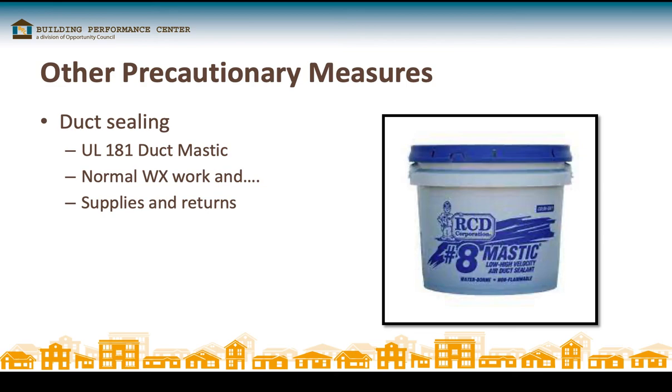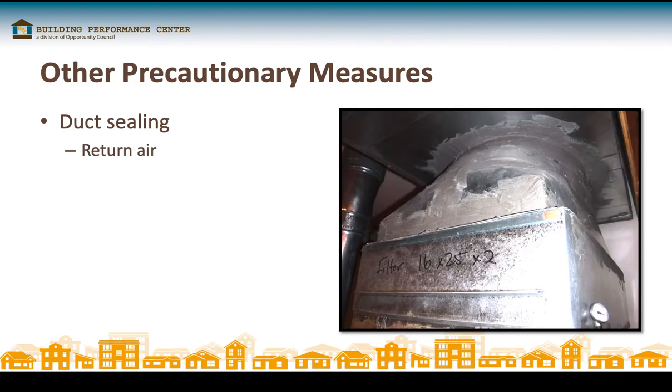All right, other precautionary measures you need to pay attention to: duct systems are great at moving air from the crawl space or basement up into the house. So often in closed crawl spaces, unvented crawl spaces and conditioned crawl spaces, we tend not to seal the ducts. But when you think about it, the holes in the ducts are pathways up into the building. So if you want to stop soil gas in a redundant fashion, first you seal the poly, and then you seal the ducts and seal the holes in the floor, and you're going to probably do a pretty good job of keeping soil gases from getting up into the house.